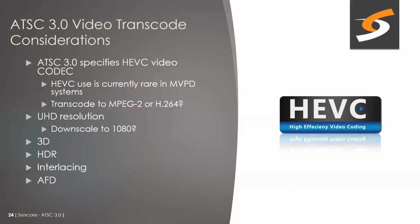If, in the next few years, HEVC support becomes much more common, it certainly could be possible to take the HEVC essence out of the ATSC 3.0 signal without transcoding it and simply repackage it into a transport stream, without doing the full decode, re-encode, transcode process in the middle, certainly saving some processing power there.